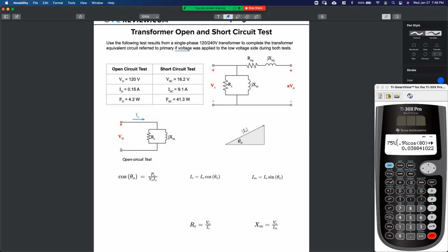Very important. Now, question, remember that part of the circuit I just drew? This is our voltage ratio, right? If I wanted to show the voltage ratio on this circuit, where would it go? If I was going to show 120 to 240, is it going to be 120 to 40? Is it going to look like that? No, right? It's going to be 120, here's our transformer, to 240, N1 to N2. All right.